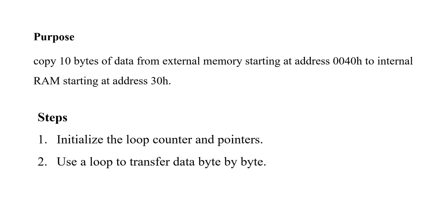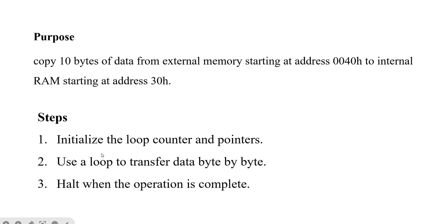So these are the steps for the program. First, we have to initialize the loop counter and the pointers. Next, we have to use a loop in order to transfer data byte by byte, and then we have to halt when the operation is complete.